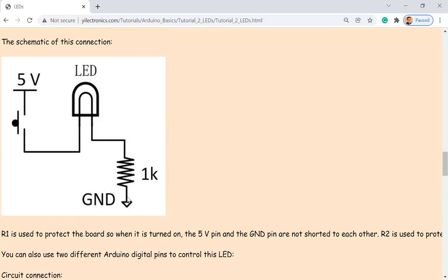So a resistor to protect it, and a push button connect this LED to 5 volts. And if you press the push button, then what's going to happen? The LED will be turned on, and here's 0 volts. Why is this not 0 volts over here? If I don't press the switch, it's disconnected from here. What is the voltage here? Why?